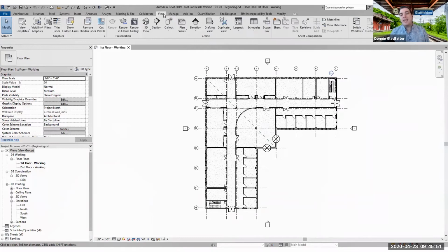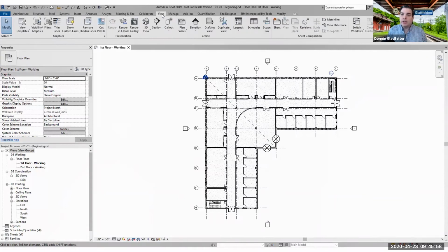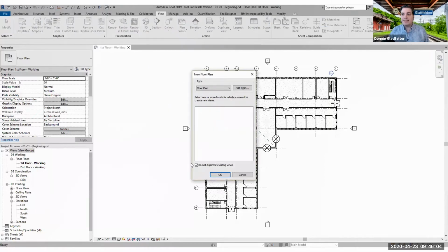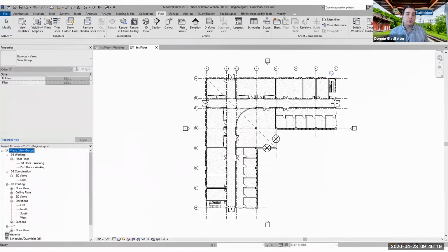And so once we have those displayed in the model, now we can start setting up the coordination between Revit and Civil 3D. Now, I know you do all sorts of awesome work to make the inside of the building look phenomenal, but on the civil engineering side, we're not so interested in that. We're really interested in the footprint of the building. So with that in mind, we're going to set up a view inside of Revit that's going to more closely mimic that.